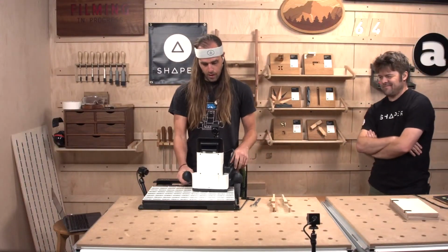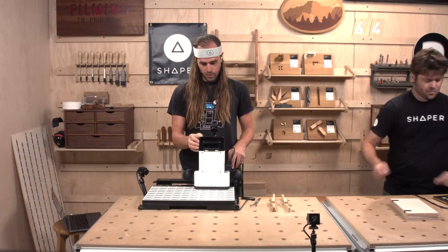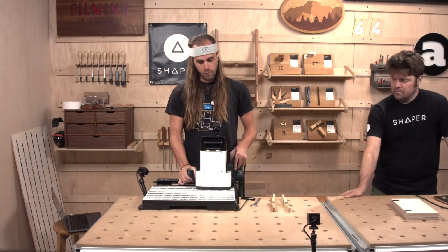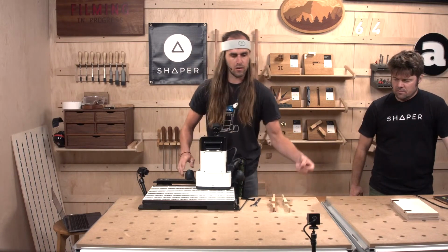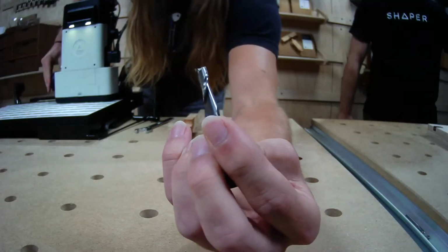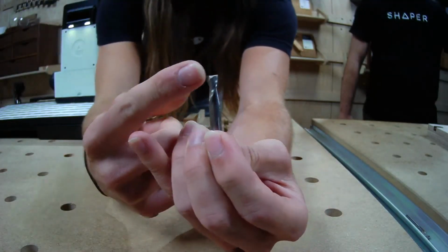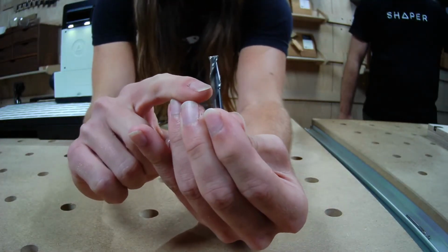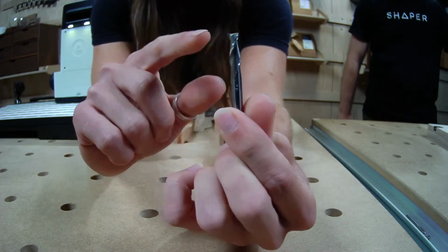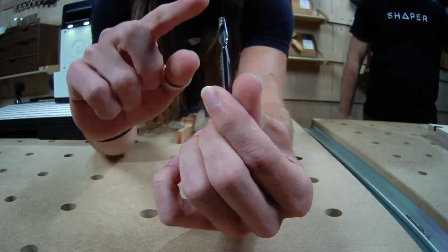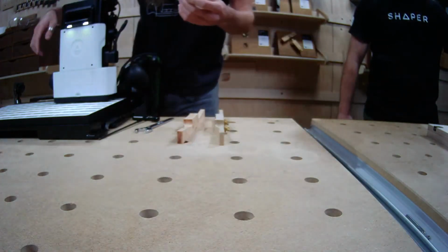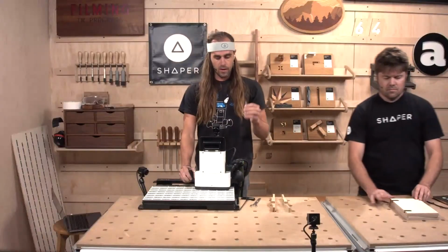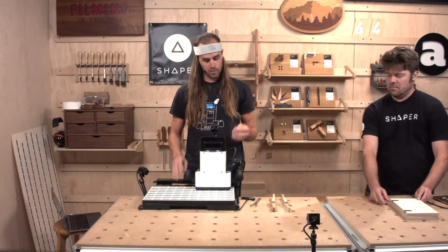I'm going to quickly talk through something. Maybe while I'm cutting, Sam can explain it. But each bit we use, and I'll come over to here, maybe the bench cam in the front here, there's a certain amount of cutting flute length. So if you're new to using Origin or routers, you can't cut with this whole thing. You can only cut to where the sharp edges go to. And in the case of the stock bit that we use, that's a 3/4 inch depth. So this material is a little bit deeper than that.